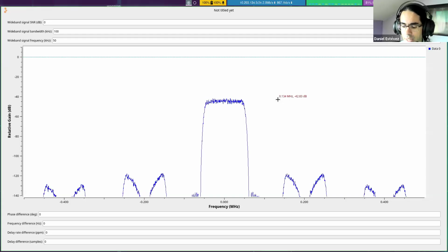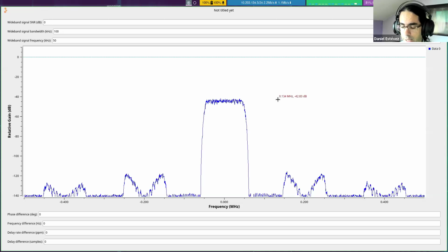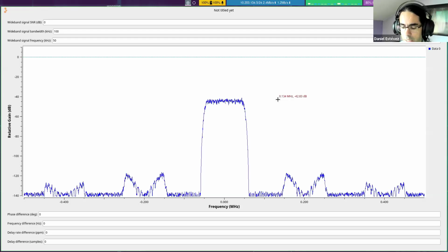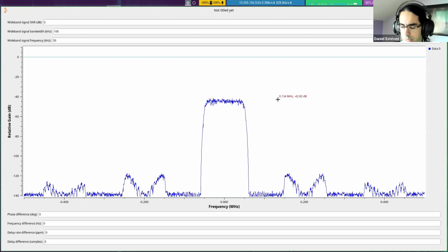And the reason why that happens is that there is a carrier wave at the carrier frequency. So we could think we are doing our observation at 1 gigahertz carrier frequency. And then that has a carrier wave of 1 gigahertz, which has a wavelength of 30 centimeters, more or less. And this carrier wave is affected by the delay.